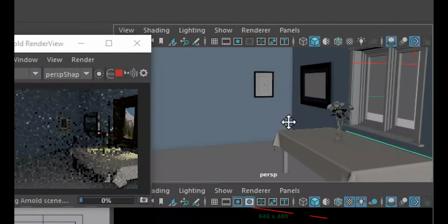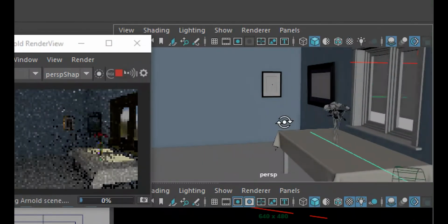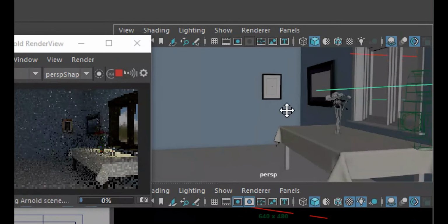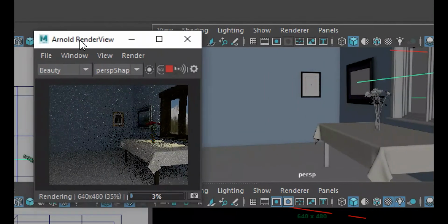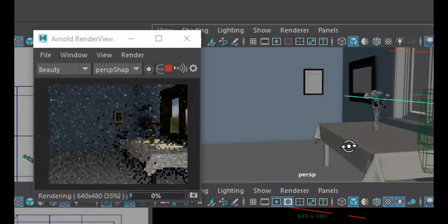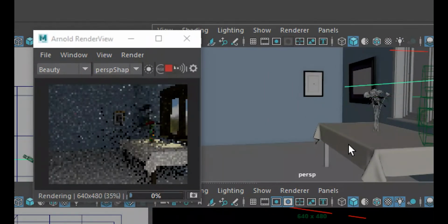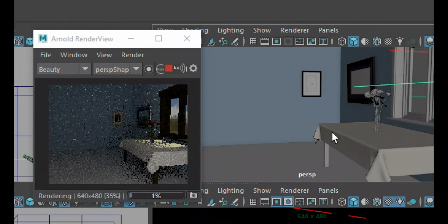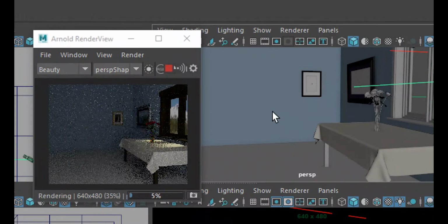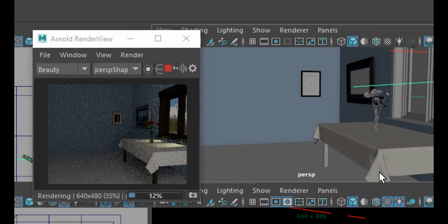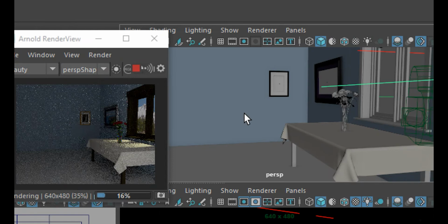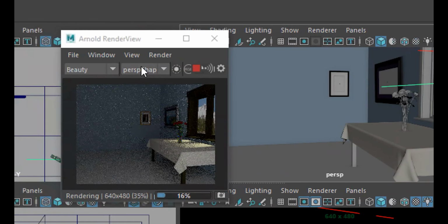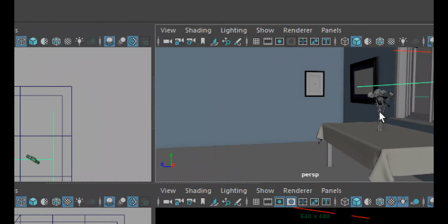I'm just telling you this because even if you don't have a window or any other opening in an interior room, if you'd like to give a feel as if there is a window or a door there, how can you do that lighting? It's not that just because you want to light that area, you have to model that object. You don't need to model anything. We can just create a fake light even if there is no window or door there. Let's see how to do that. I'll stop this render. I don't want to waste my memory.